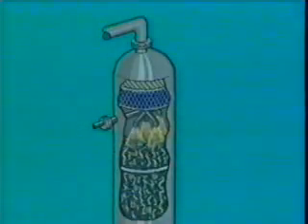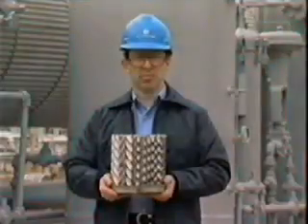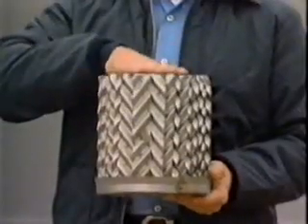To ensure that gas and glycol mixing will be continuous throughout the packing and the glycol will not channel, a well-designed glycol distribution header is installed above the packing. Contactors being designed today may contain structured packing.